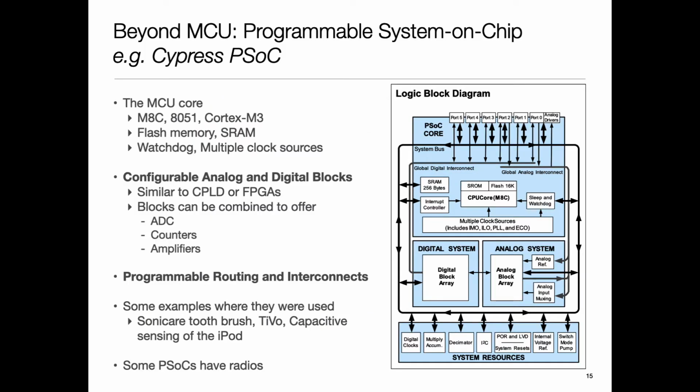Beyond microcontrollers, there are other more boutique forms of computational units. Sometimes, in addition to a processor core, they put some hardware which can be configured. So it's almost like, in addition to software, you also have hardware which you can wire by appropriately programming it, doing the wiring in software. FPGAs are a great example of it, but there are other variants of this. Common to all of them is some sort of logic building blocks which you wire up.